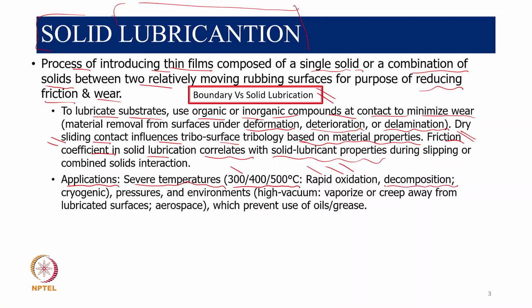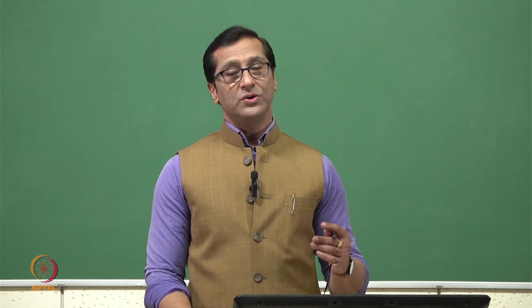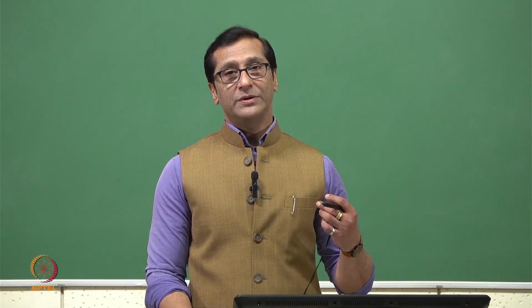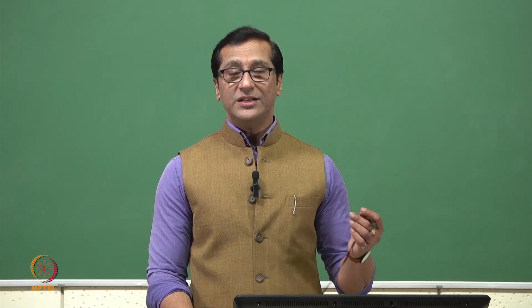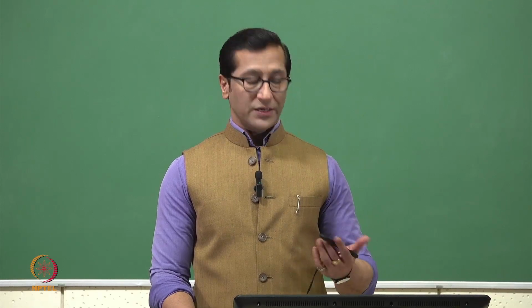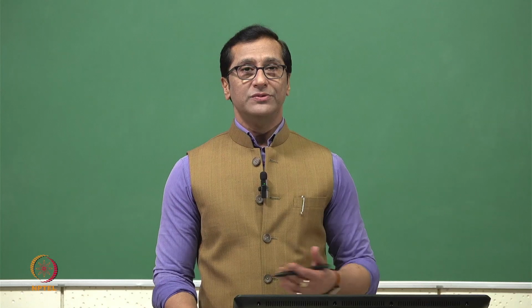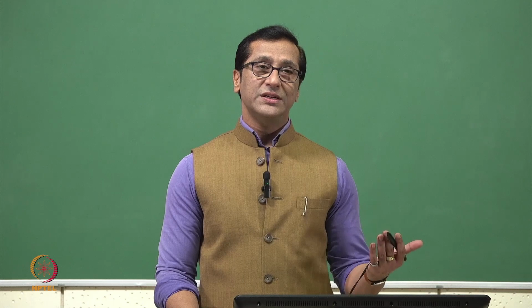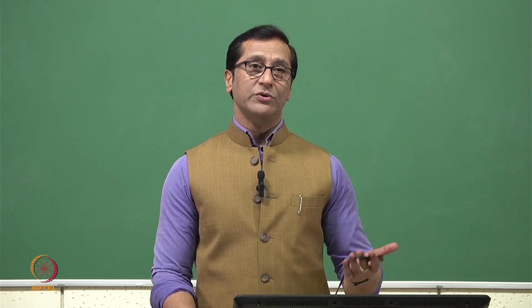Similarly, at high temperature, even the substance decomposes. So if the mineral oil or additives which we are using start decomposing, then there's no point in using that kind of liquid lubricant or grease. Even in a cryogenic situation, the low temperature viscosity goes very high and freezing occurs. Naturally, in those situations we again don't require a liquid lubricant or grease.